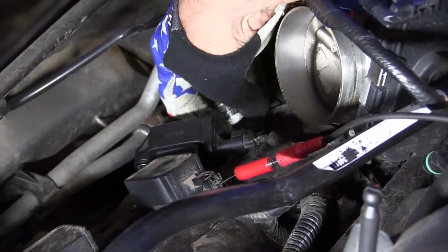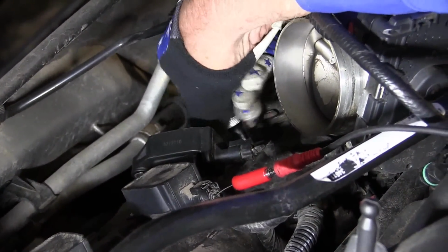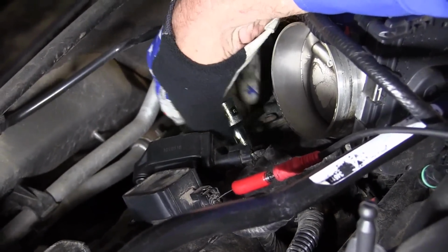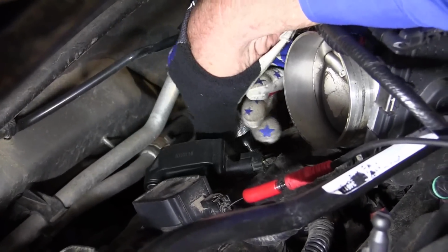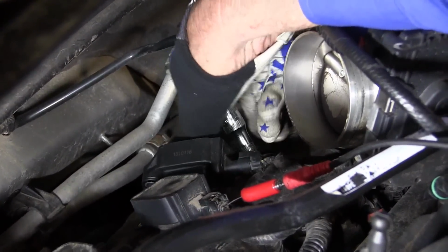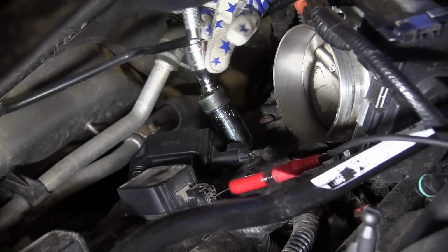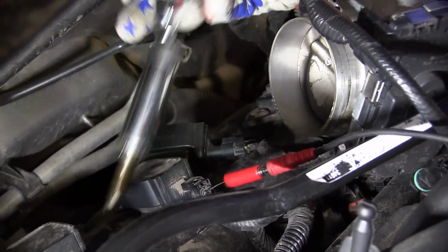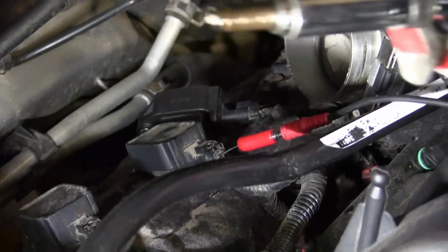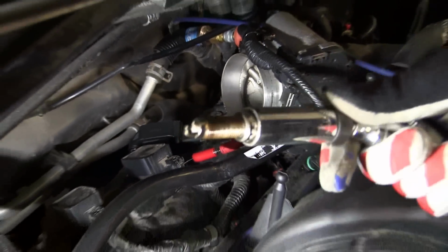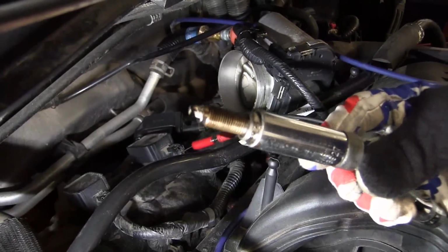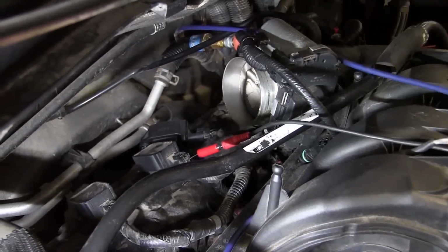Okay guys, I'm taking out the spark plug on cylinder 5, and we can see that there's a brand new coil on the cylinder 2. This is the dead hole that doesn't fire at all. They've been trying to fix this. Oh yeah, that plug hasn't fired at all. It's new and it hadn't even fired.